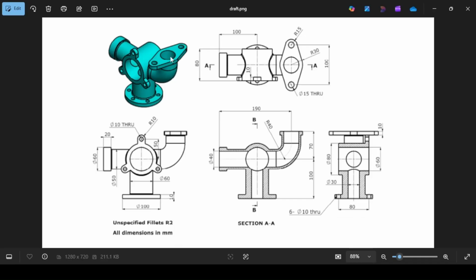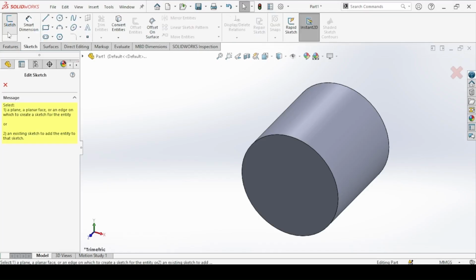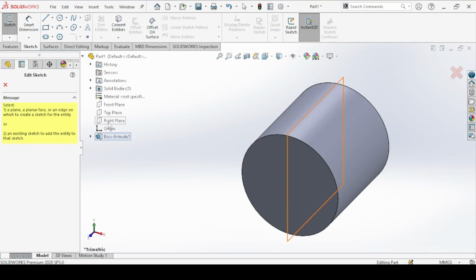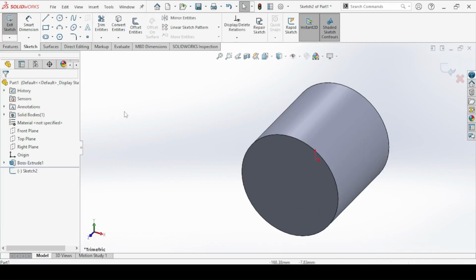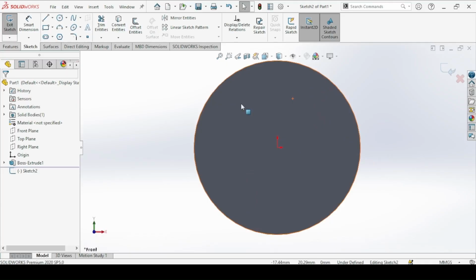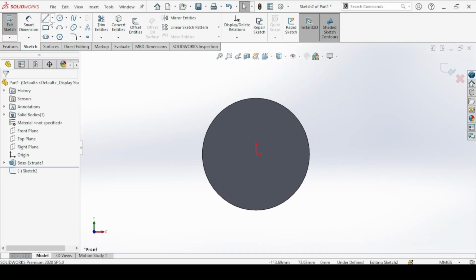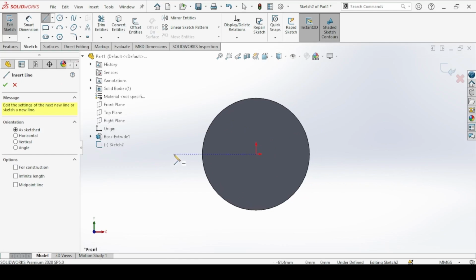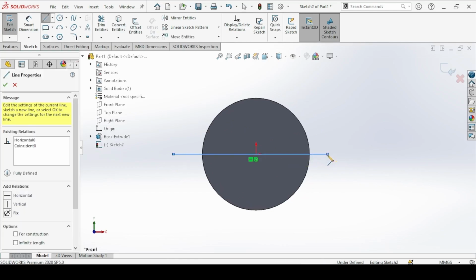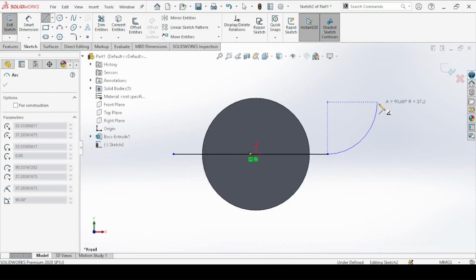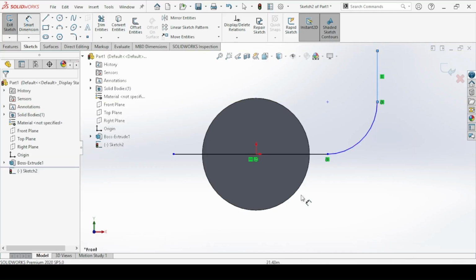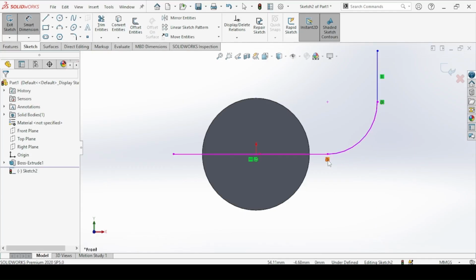Next we add the curved pipe. So we are going to create a curved sketch and then sweep a circle around the curve. So we create a sketch first, and this sketch should be on the front plane also. With the line tool, you first draw a horizontal line. Move your cursor up, come back to this point. You can now draw an arc and then a vertical line. Now let's dimension. You make sure the tangent relation is showing on these 2 points.